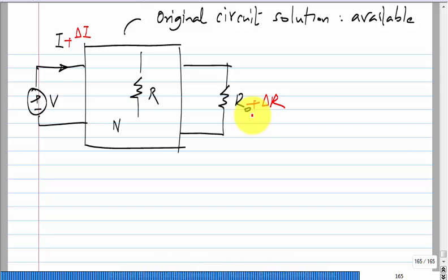One of the other things is that, let's say you specify a number of resistors. So let's say your circuit uses like 100 1 kilo ohm resistors. It's not that every resistor will be exactly 1.0000 kilo ohms. Okay, each one will be different in some way. Okay, this is known as mismatch. Now they may be off by 1%, they may be off by 0.1%. That depends on the construction, but they will be different. And there are circuits in which that will also affect the performance. Okay. So in general, it is of interest to find out if some component changes, what is the effect.